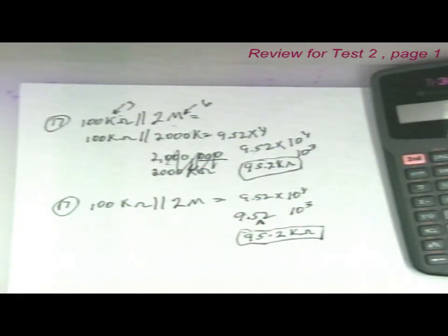Okay. A formula that applies to a two-branch parallel circuit is what? How about RT equals R1 plus R2? No, that's not right, is it? How about VT equals VR1 plus VR2? That's not right. How about IT equals IR1 plus IR2? Yes, that's right. Because the currents are additive in a two-branch circuit, aren't they? They come into the node. You have a certain current. Let's say you have 6 amps, and the current going out is going to be 6 amps.